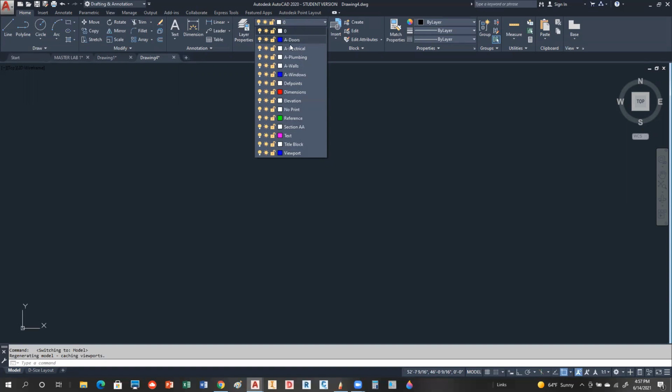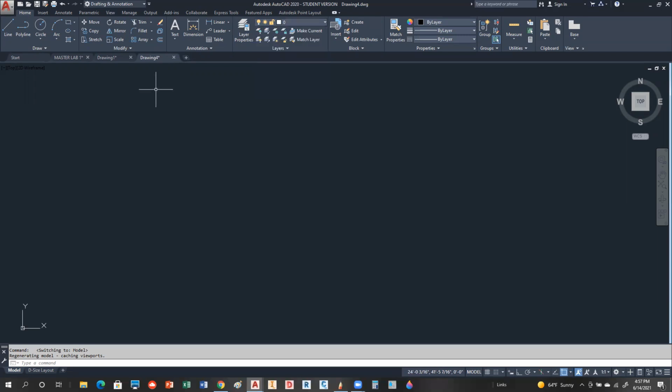So people in industry will use templates because they don't want to recreate the wheel every time they start. So if you're working in a company, and you have enforced rules, like certain color schemes you want your people to use, and certain line types and those kinds of things, you can create a template for that company, set that as the current template, and then you can go with it. So any AutoCAD drawing file can be a template file.